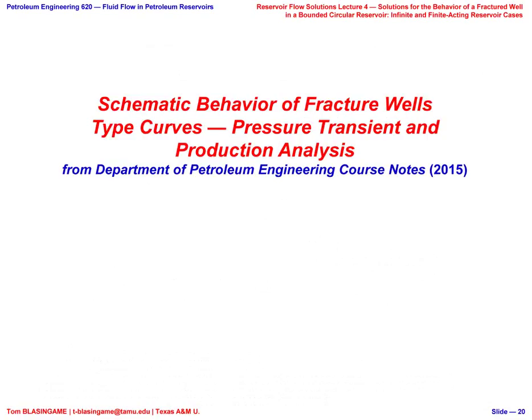How would you go about creating a multi-fractured horizontal well solution? Anybody? How would you do it? Geometrically, we took a line and we created a plane, and then if we integrate into the plane, we get, I guess you'd call it, a block of certain thickness. And actually, this is how they derived the horizontal well solution. They made the block be symmetric, and that would be a horizontal well. But now I want to put fractures along it. How are you going to derive that?